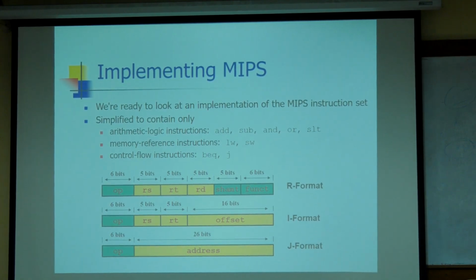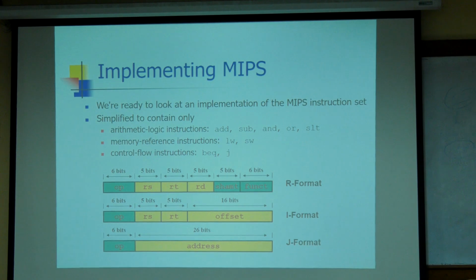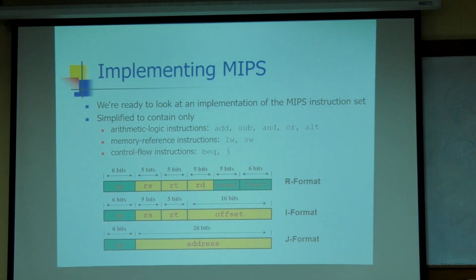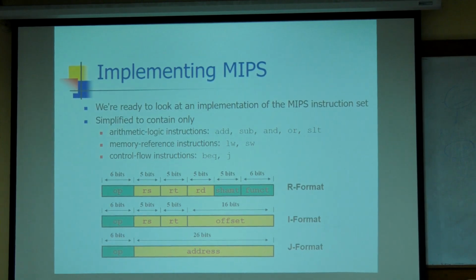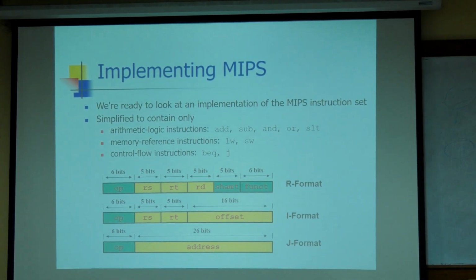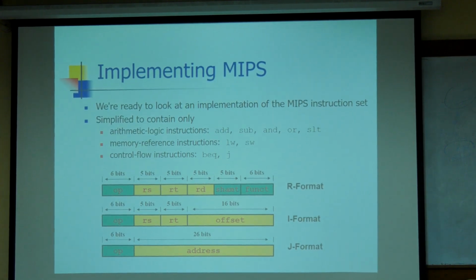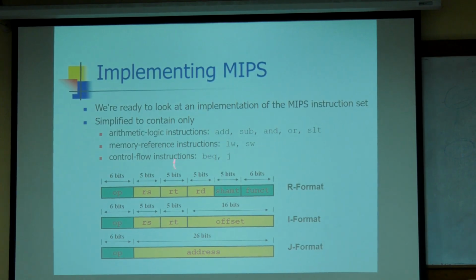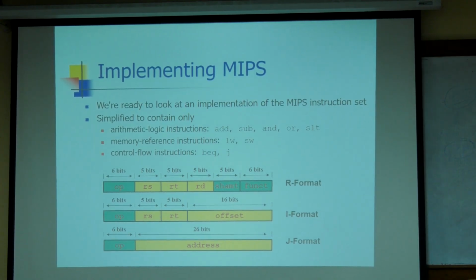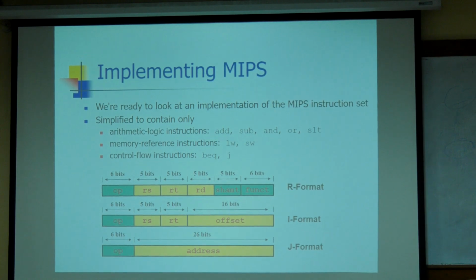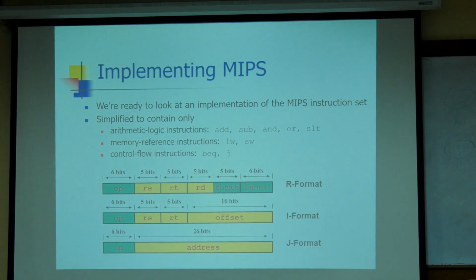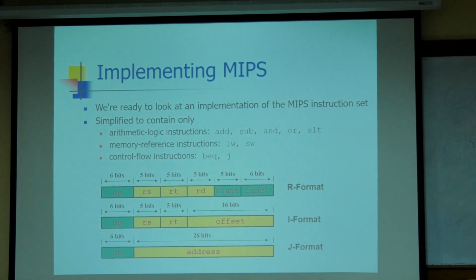These are the instructions it is going to support for this MIPS architecture. If you see that instruction template or instruction format, the processor won't understand assembly code or C code directly, because the digital circuit will follow only digital binary bit patterns, right? So finally, to write a program in assembly language using these instructions, we have to translate it into machine level language, machine code, by using an assembler.